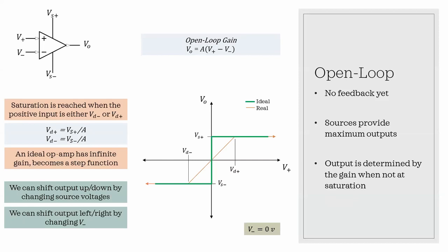So we can see right away this might be useful. If our inverting input is an important value that we would want to check our non-inverting input against, our op-amp output is at negative saturation, or the Vs minus, so long as our V plus, our non-inverting input, is below it. But as soon as our non-inverting input reaches this important value given by V reference, it switches to the positive saturation, which creates the comparator. So this is a pretty simple one, the simplest case where we don't need to do any kind of real math. We just look at the characteristics and see what's going on.